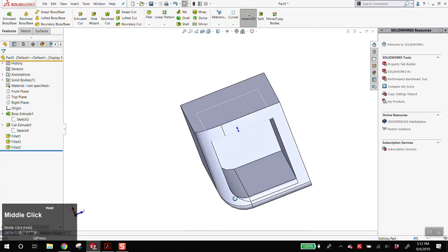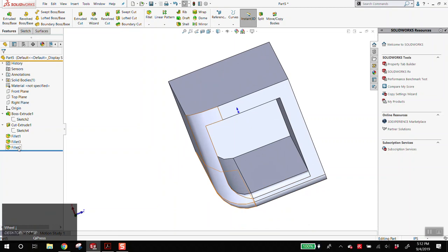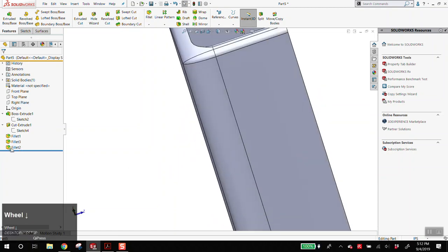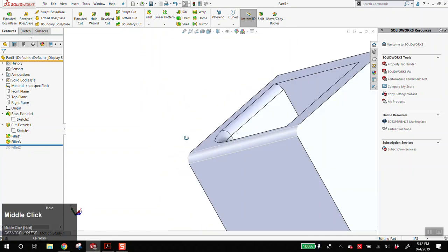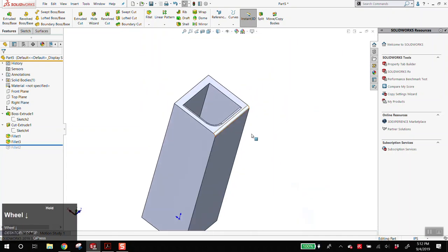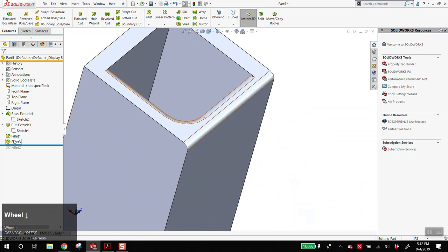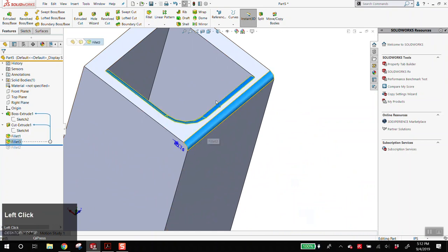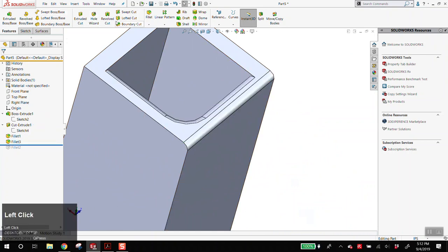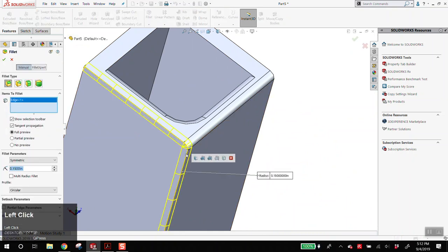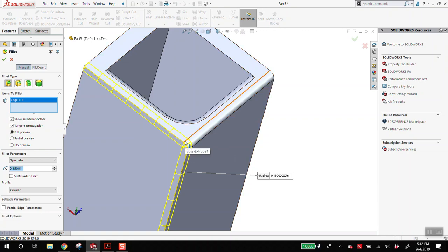For some of you, this may have actually made it blow up. It may have given you an error on fillet 2. But here, if we look at what I did, you'll notice now that by moving these 2 inside fillets to where I did, now if I put a fillet on this outside edge, it wants to turn this inner corner here. Does that make sense? So fillets flow around the tangency of the object is the simplest way to say that.